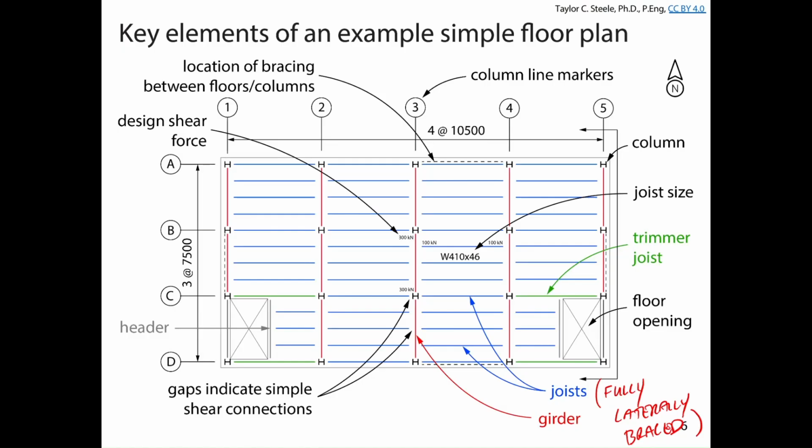And then the red elements here are all the girders, right? And we'll recall that the girders support the joists, and so the joists apply load to the girder everywhere the joists frame into the girder. Usually it's as a series of point loads.